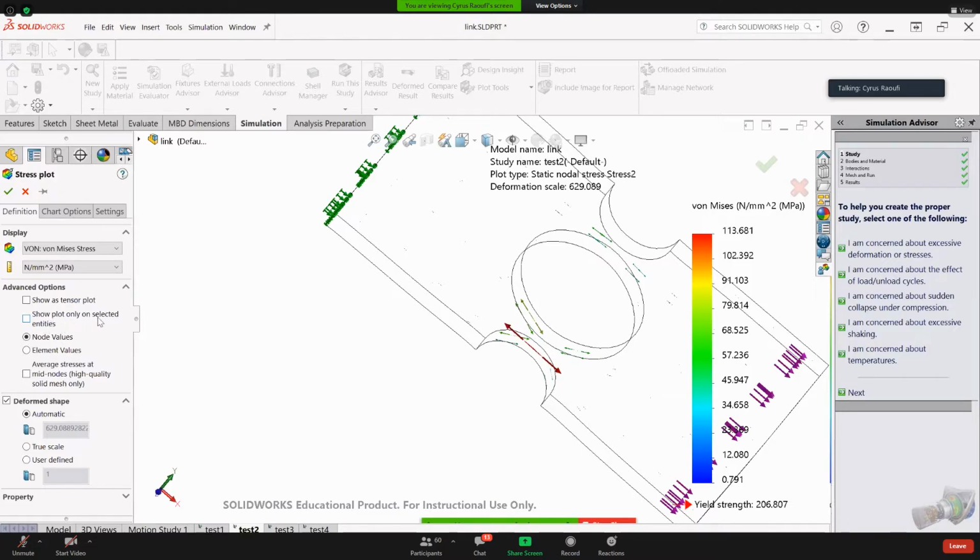this is obvious, you want to select some entities and show them. We have node value and we have element value. Let's talk about this in chapter 3, but what you see here is node value. At each node you see the result, but you can have the average for one element. This is for us in this course not a big deal because we are going to look at the node value as a default, but average means that for example, one element has say 10 nodes and each node has its own stress. Very close to each other, you may want to have the distribution based on the average, not based on for some application.